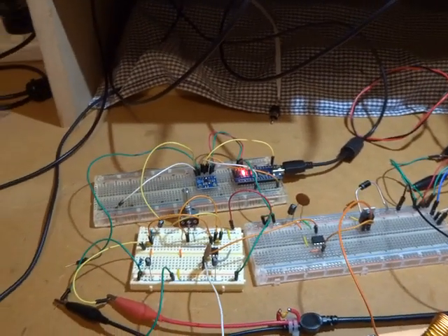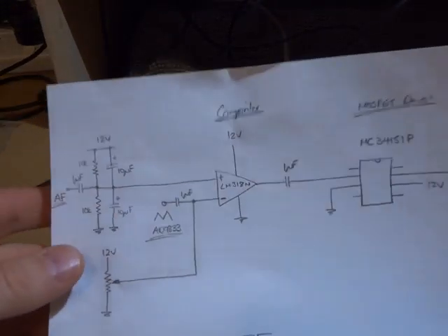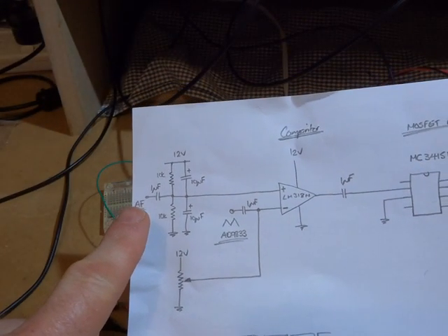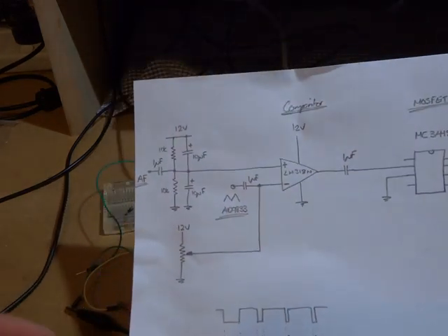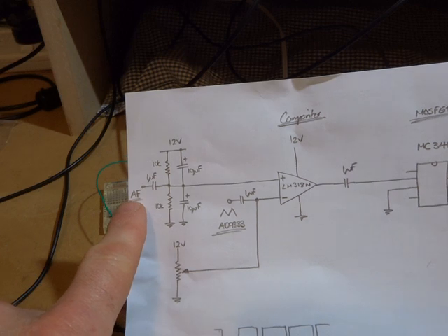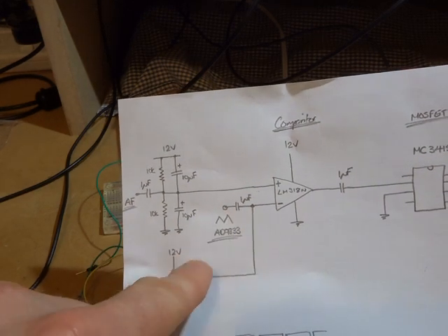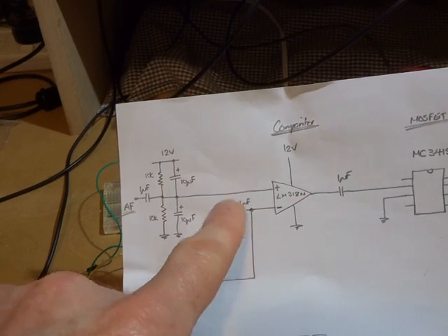Right, so in terms of the audio amplifier, it's pretty important that that audio is filtered, and we want the highest frequency coming in there to be way less than what we call the switching frequency here, or that triangular waveform there.